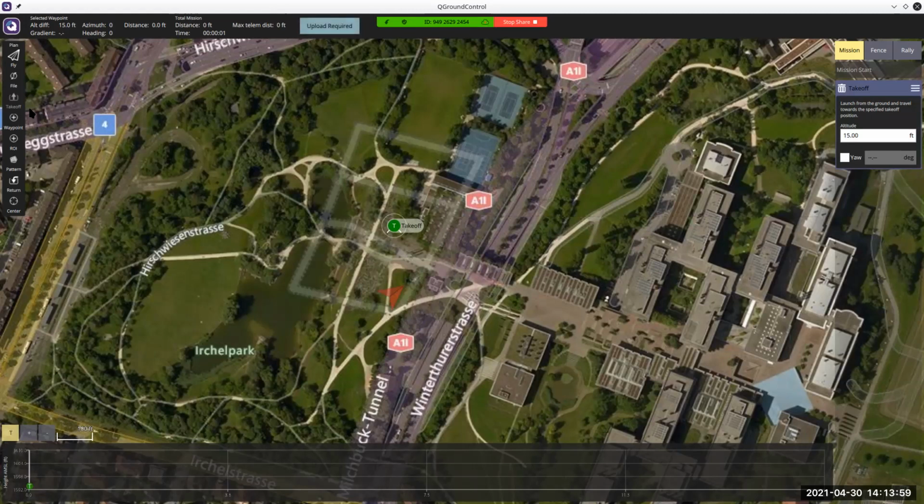And the GNC algorithms that we typically think about, which are the ones that could be optimized, are inside PX4. Is that correct? Yeah, exactly. Okay. All the internal controls are inside of PX4 in the actual simulation, and all QGroundControl is doing is providing an interface to take advantage of the algorithms that already exist. Yep, got it.